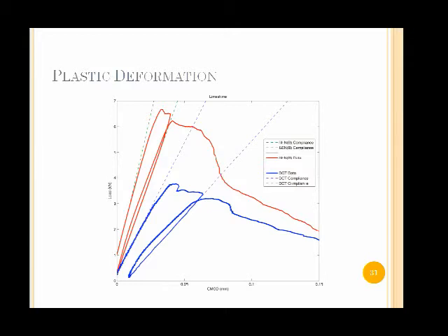So there's no age issue or mix issue with this. We're thinking that possibly this larger plastic deformation nonlinear effect could be causing those lower K1C values, because it appears that there's more of a crack extension in there that we may not be capturing, just because it's difficult with this test and the loading rate we have to use to be able to immediately unload this specimen.